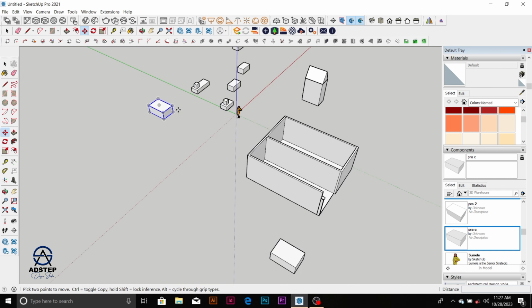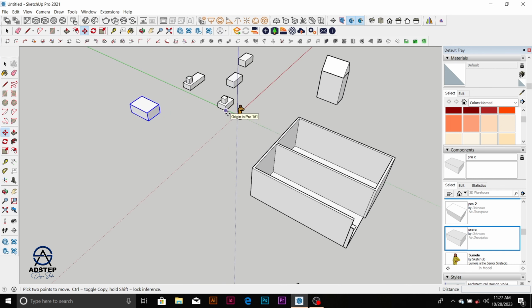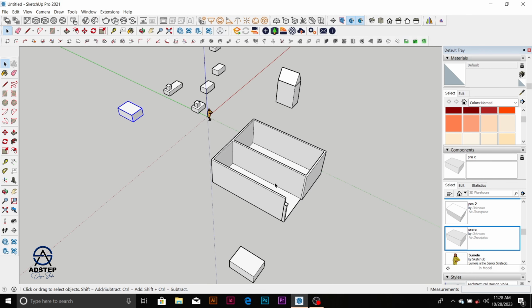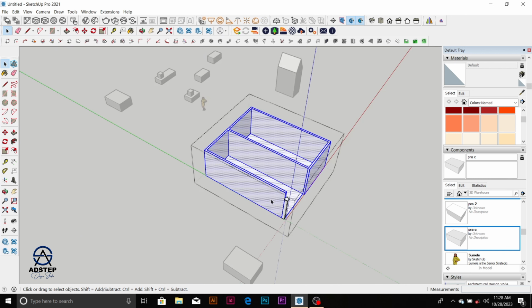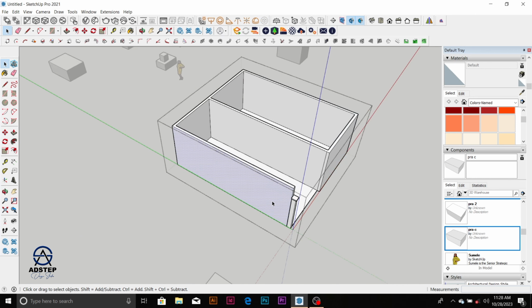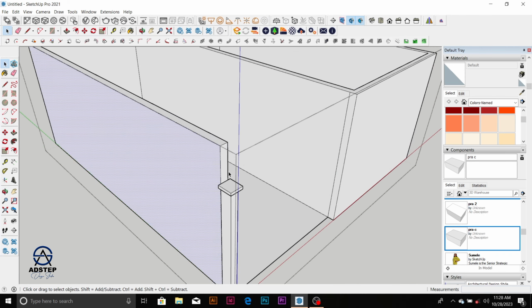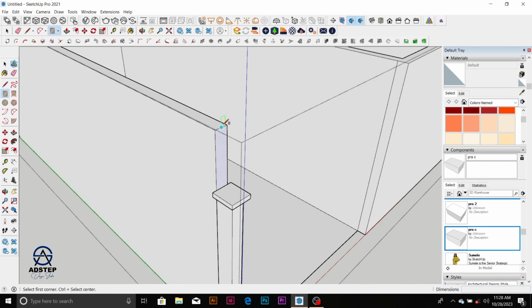So there's an advantage of making a group a component, so that it enables us to reuse it. It encourages reusability. Let me show you how to make the transition. Maybe I want to enter this component now. Double click it. Click what you want to edit. Maybe you want to edit somewhere. I want to raise this place up. And just edit it.